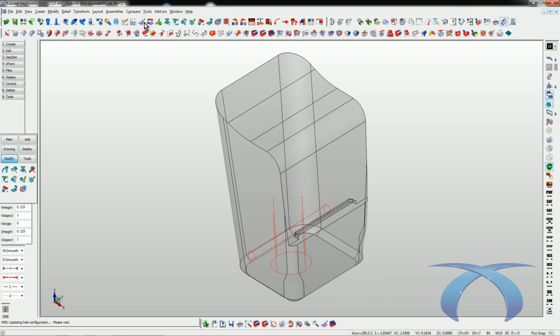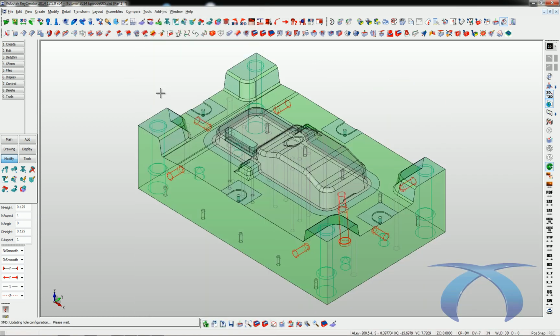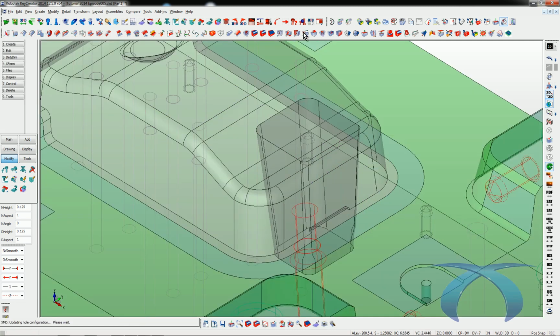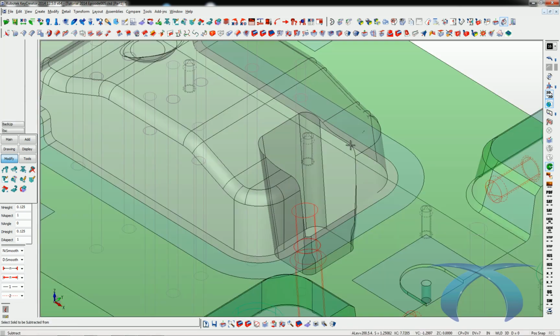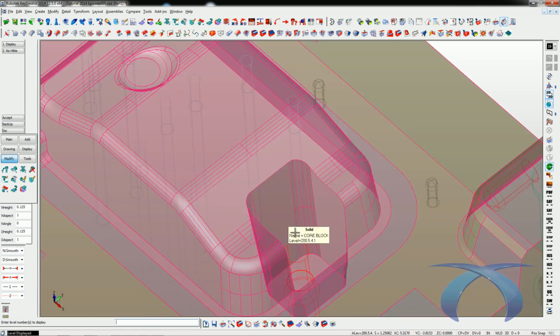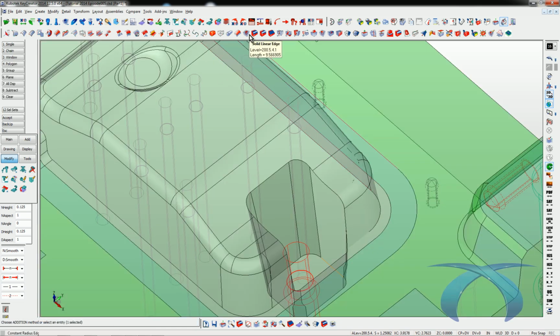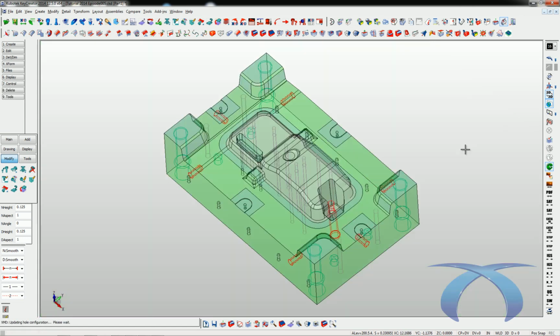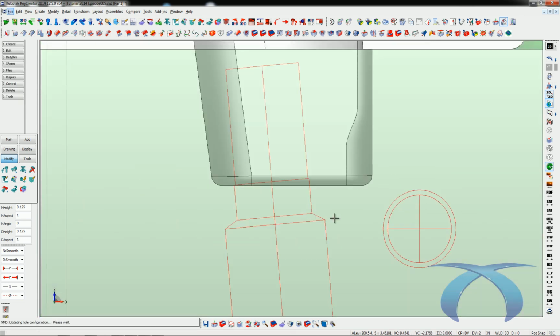Do that, and then I'm going to pull up my core block. And I'll pull up that solid that I copied, right? And I'm going to subtract that from my lifter. Okay, just like that. And I'm going to put a little 1/8 radius down there in the bottom. So do that again. Select the invalid line. There we go. So now we have radius down there at the bottom.